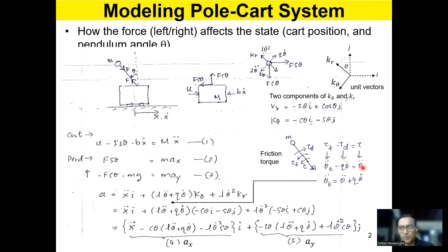What you see is only this one, theta double dot. However, if you look at it from the energy perspective, it is tau t, the total torque, which goes in, and it is this tau torque that comes out as an outcome. Okay, so in your equations, we need to write down components referring to the total torque here. Otherwise, there would be an energy imbalance in your equations, right? So keep that in mind.